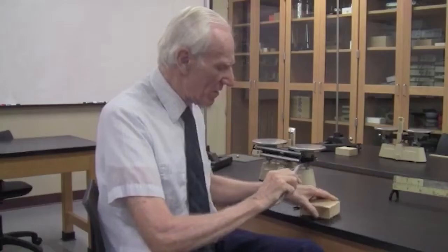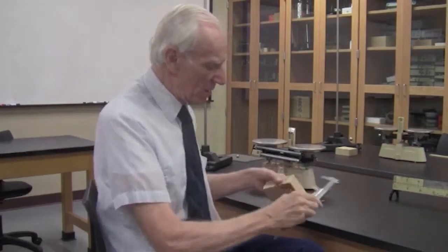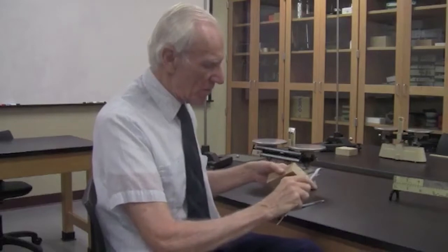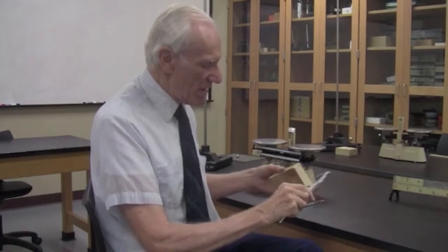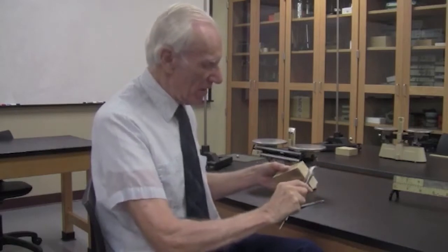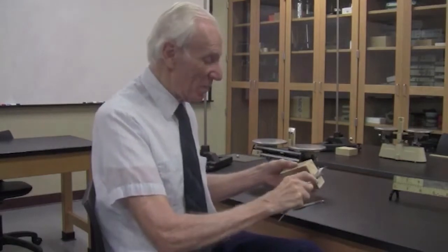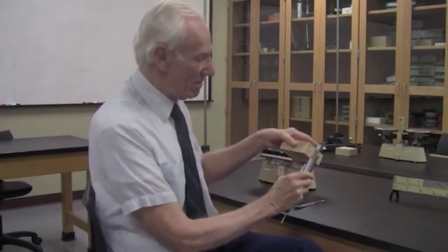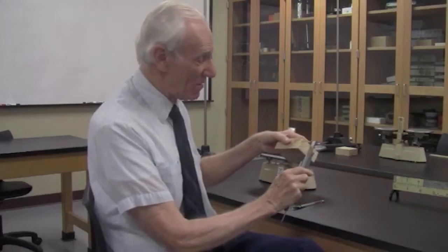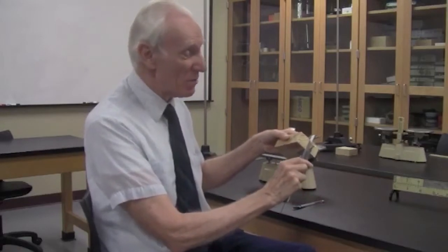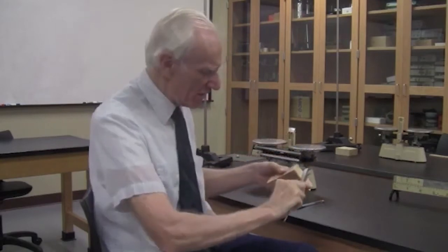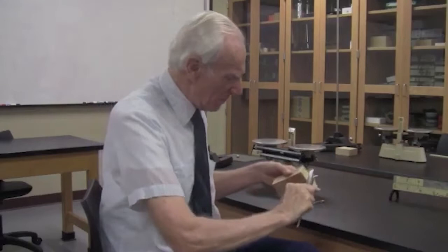So let me put this block in, and this is the way you do it. This has got a little thumb adjuster here, and when you let up on it, it kind of locks that in position. When you push into it, it allows this to move. One can let up on it and take it off and read it, but if you do that, it's pretty clear that your reading is going to be a little bit on the high side. Since this can measure to 2/100ths of a millimeter, you want to keep tension on that and read it while it's under tension.